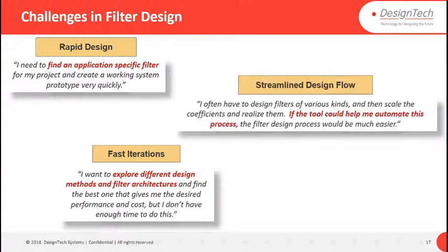Third thing, I want to design a filter for streaming, means I want to scale the filter coefficients. Means as a default, when you design the filter in MATLAB, or any software if you are using, that will be a floating type. So how to scale that filter? I want to define the word length of the coefficients of all the parameters of my filter, right?